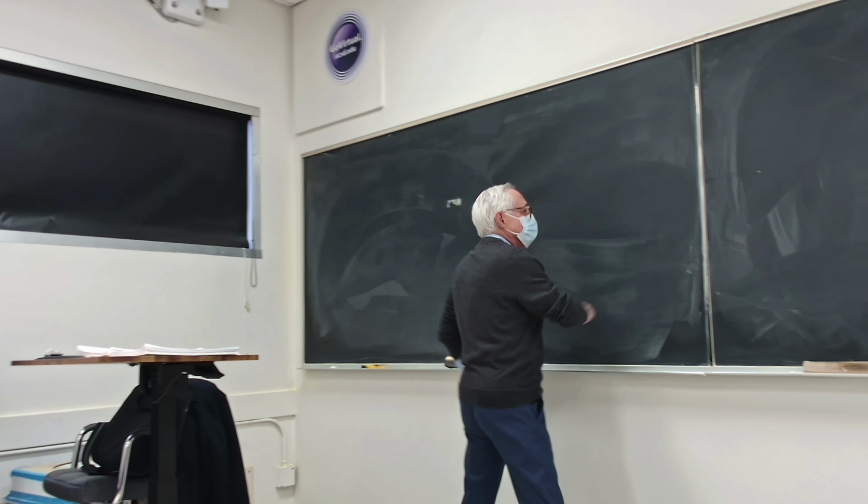And this steam loses energy to this outer fluid around it. It does not have to be a single tube, it can be multiple, going back and forth until it gets out, to increase the exchange area for heat.